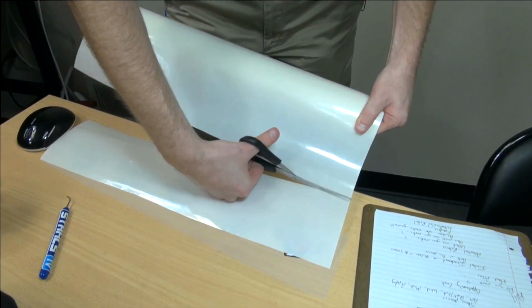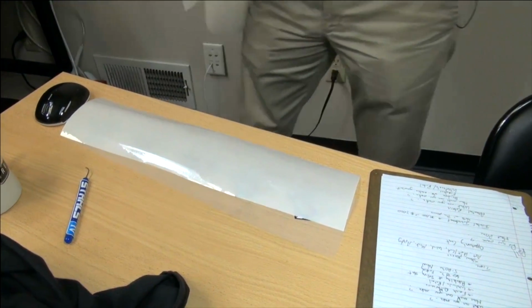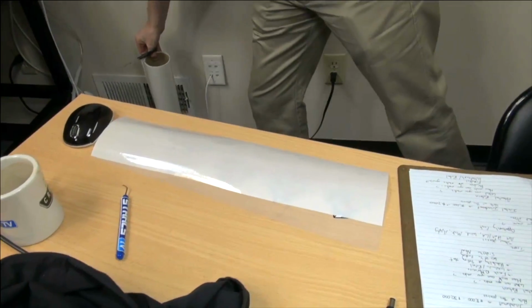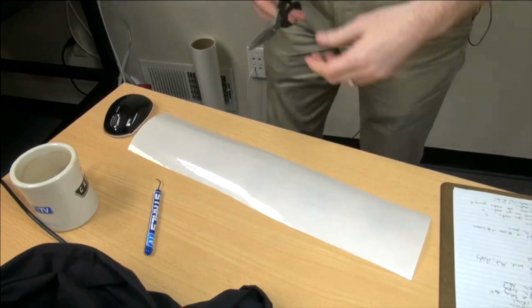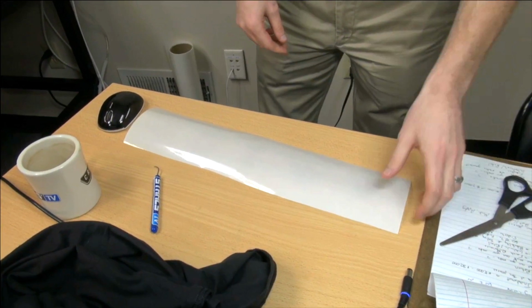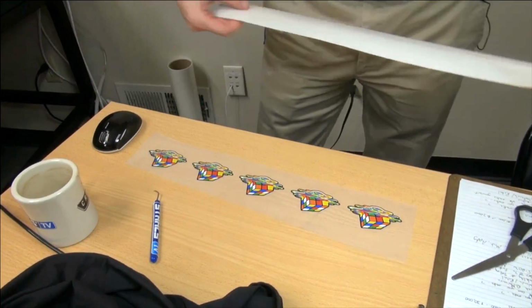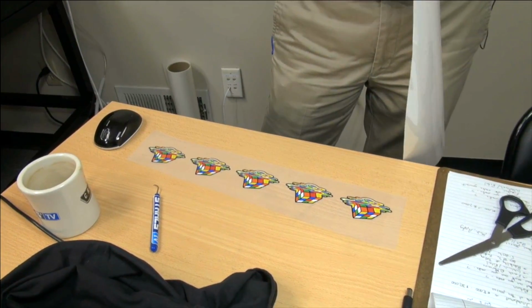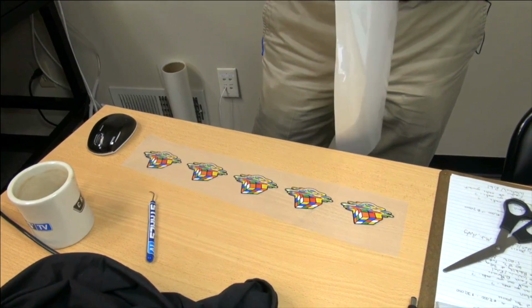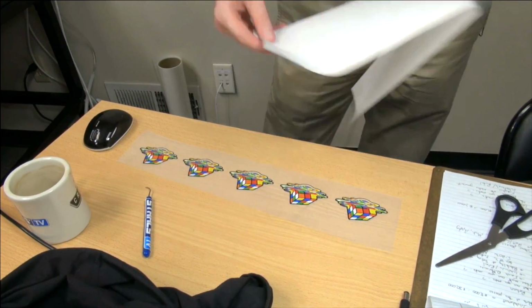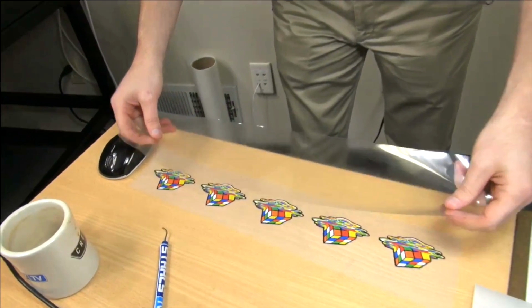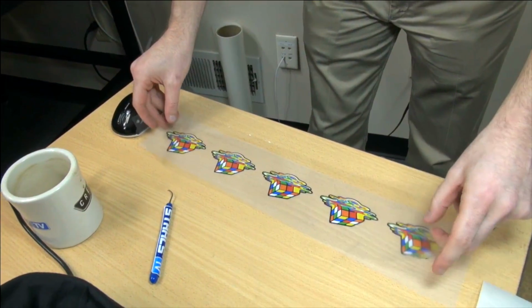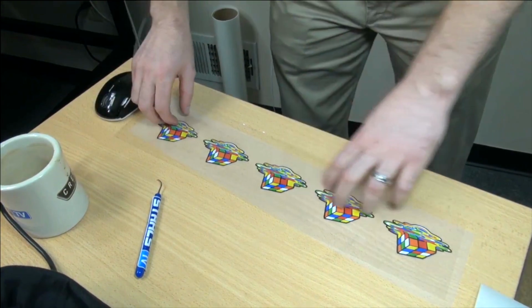Okay, we have a question. Can you use scrap pieces for printing 1 or 2 designs? The answer to that question is yes, but carefully. Specifically on the BN20 machine, it doesn't deal quite as well with waste as the larger machines do, just because of the way the pinch rollers are set up. But yes, you can use smaller scrap pieces and print to those.